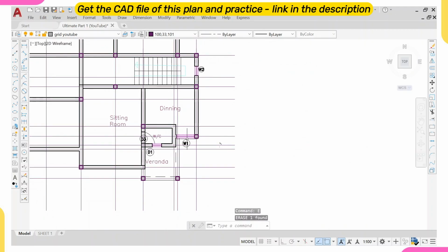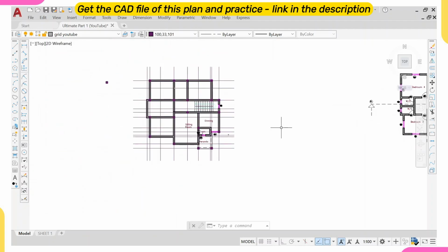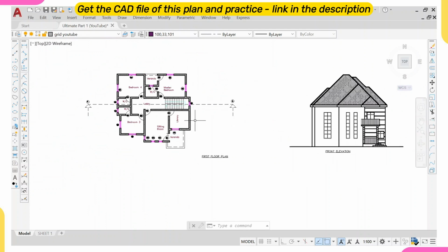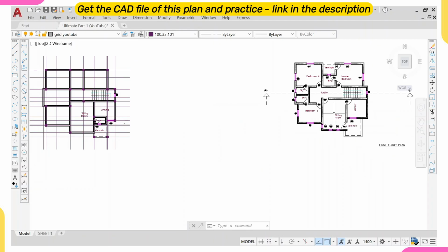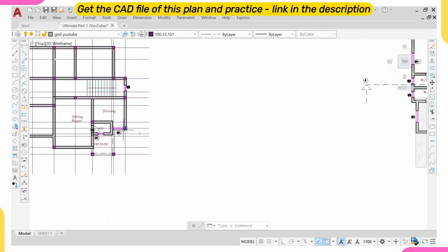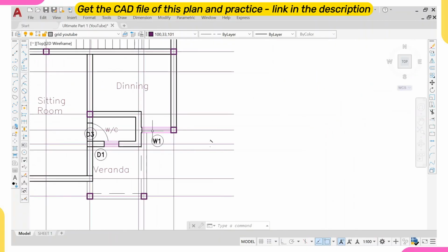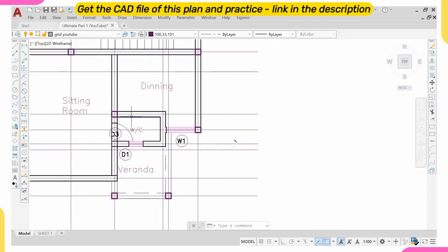So coming to this point, how are the beams being run? Are we going to have a beam separate from here, then run like this, run like this? To determine how this beam will run here, let's go to the second floor and know what we're having at story one. Okay, so look at this point here. If you see now a column, we're having wall load straight. That means I would like this beam to run straight, to be able to carry that wall load. This is part of the reason why I say you should study your architectural plan.